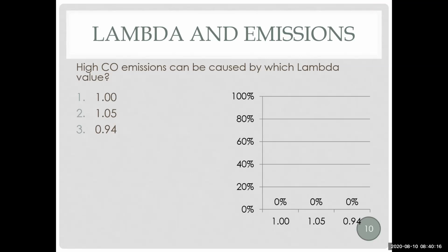So Mr. Bryan, by getting rid of carburetors, more likely everything's going to run a lot better. Oh, absolutely, because carburetors are very, very hard to control the mixture, for one. Two, they're not efficient, which means my CO2 level is never as high, or almost never as high, on a carbureted vehicle as it is on a fuel-injected vehicle, because they're just not that efficient. So my emission standards are normally higher on carbureted cars than they are on fuel-injected cars.